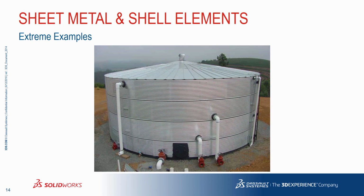So it's definitely worth it. And again, something like this looks daunting at first. I know a lot of first-time simulation users really want to get into it, and they open up their largest top-level assembly and want to apply the grain loading, the pressure loading, the weight, maybe a wind loading, and they want to go to town and get their answers, which is great. We just have to take a step back and realize that there's some prep work we have to do.